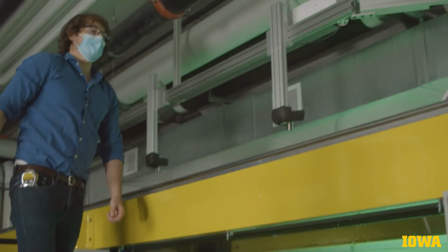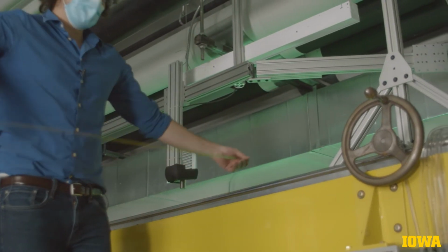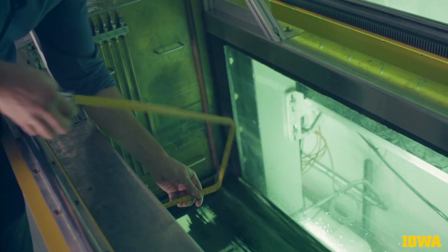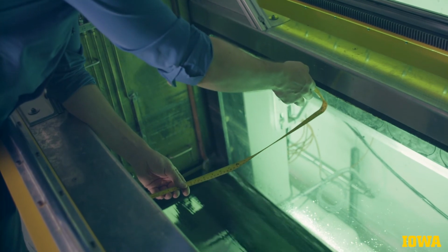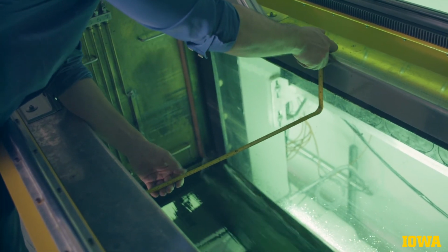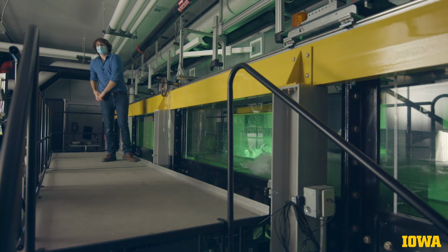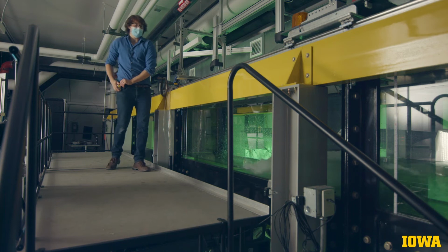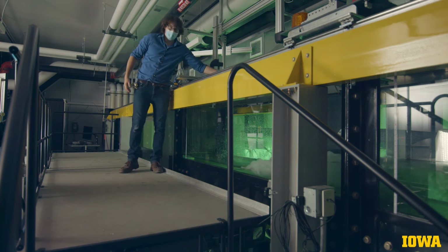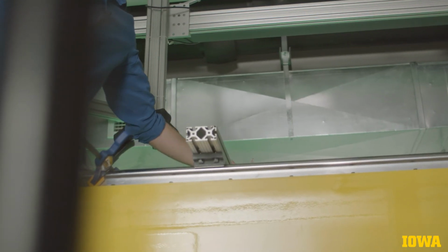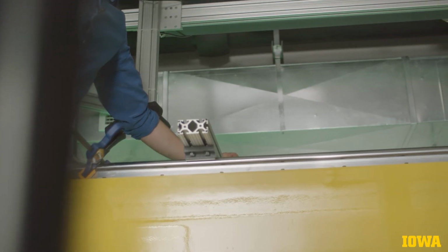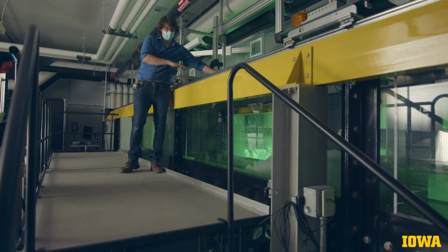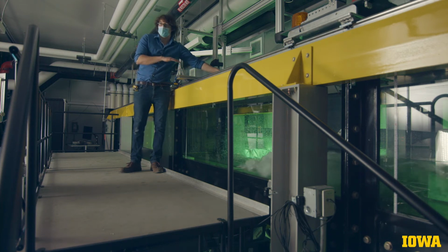gives us 49 centimeters. The width of the flume is likewise, again measured using a measuring tape, showing 24 inches. And the measurement of the water depth downstream is obtained using this needle gauge, which can be raised and lowered, and is calibrated to indicate the distance of the tip of the gauge measured from the bottom of the flume. Presently, the gauge indicates 0, showing that the tip is touching the bottom of the flow channel.